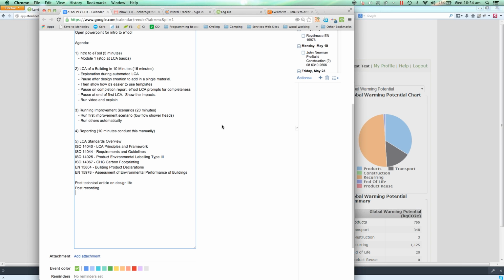Yeah, so the other element to that would be how the thermal performance is going to change for those different buildings. So thermal mass. That's right. Yeah, thermal mass isn't as important for commercial buildings, but for residential buildings it actually becomes quite important, particularly for a region like Perth, which has such a good temperature range. On an average day, you can usually benefit from some natural ventilation and storing a bit of temperature in the thermal mass. But there's no reason why you couldn't do that.